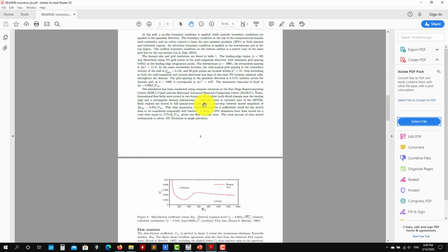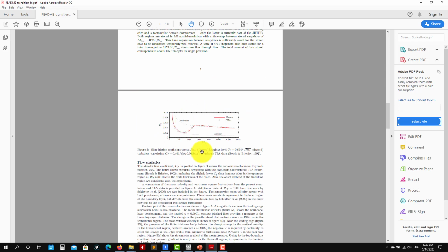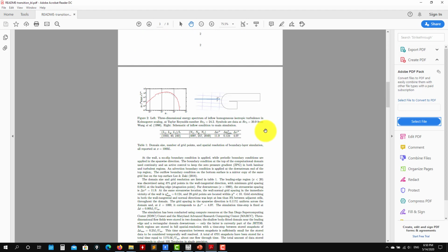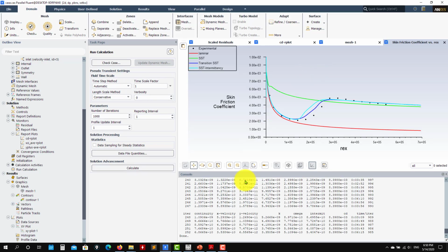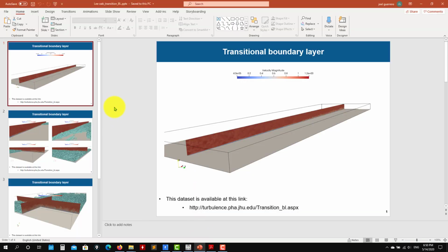What is interesting in this solution, which you can find as a PDF on the internet, is that you have the same values, and you see the laminar solution, the turbulent solution, and the onset of the transition. This is just to stress that this is a DNS solution. It's an extremely fine mesh. If I recall, it's like 1 billion or 2 billion cells to get that. So you see here the advantage of using turbulence models, just to reinforce why we want to use turbulence models.